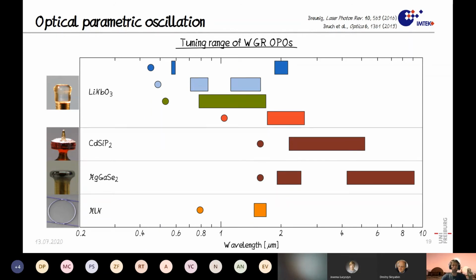And here I really want to highlight one more experiment, not from our group, by a group at Yale, Hong Tang's group. They have recently demonstrated a chip-integrated version of a second-order nonlinearity-based parametric oscillator made of an aluminum nitride ring. They pumped it at 800 nanometers, and they generated some tunable light around 1.6 micron wavelength. So these things can be integrated on a chip, so it's very nice work.